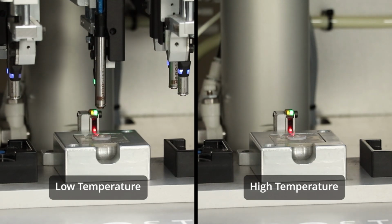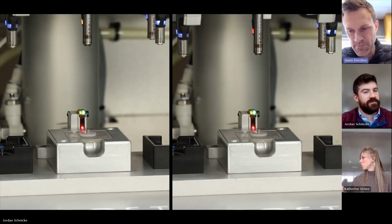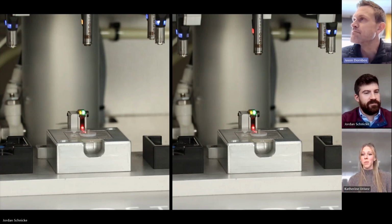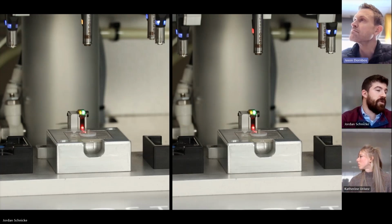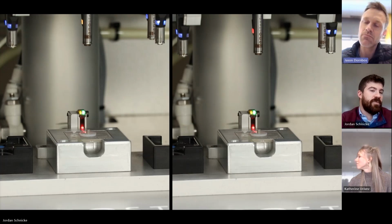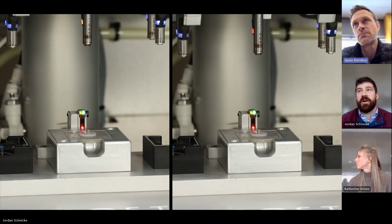Right. So if you're having that really long cycle time, like you had mentioned, it might be a dwell position thing, or maybe you just want to try bumping up your melt temp. Or alternatively, as you mentioned, the cool temp, right? So it's going to melt faster at a higher temperature. It's also going to cool down at a higher cool temperature.